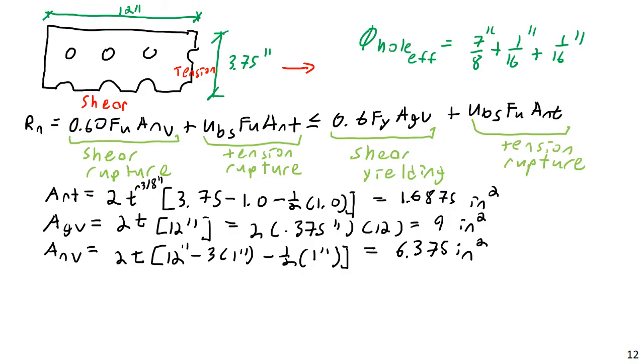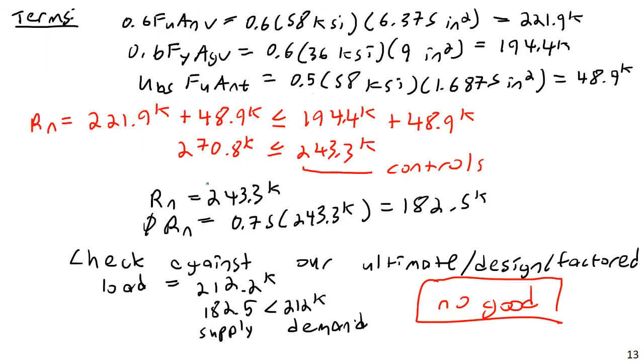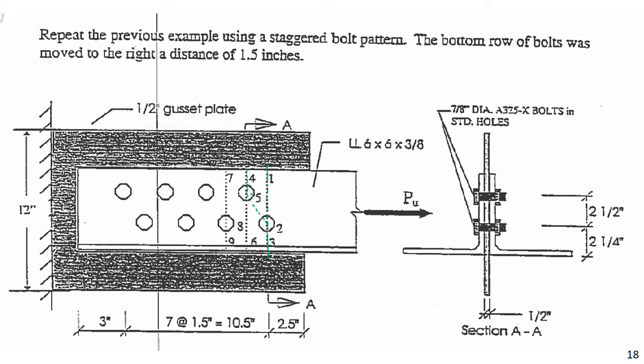When we do the tension plane, we're doing this based off of a net tension, right? And so it's going to be in tension here, and it's just not going to generally change that much. Even if it goes like this, we don't get to take into account that extra diagonal, so we just consider its length to be about the same.